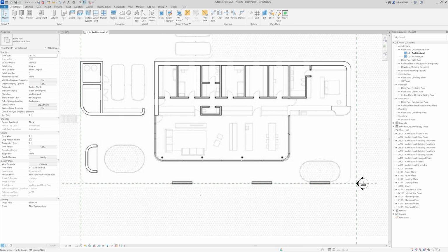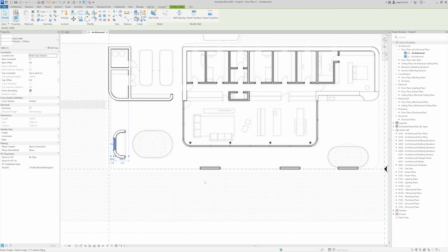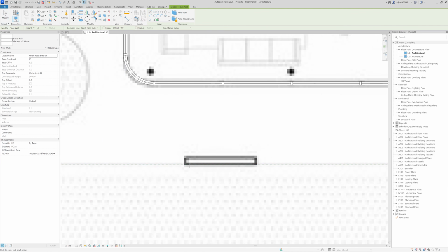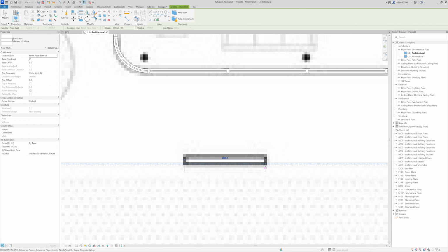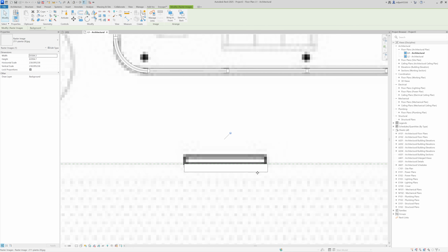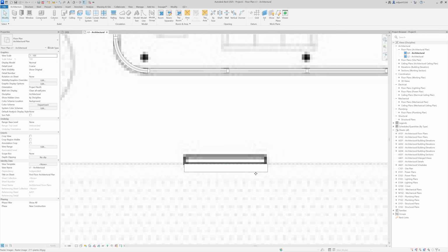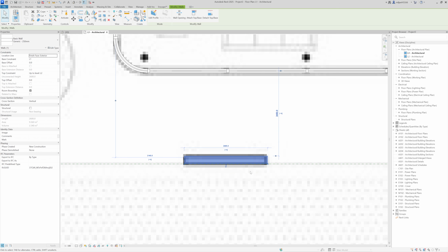And let's just make those walls here so they have the same dimensions, the same thickness as I can make it 2.6, let's say. I forgot one thing, and that's to change the orientation. So just hit the space.